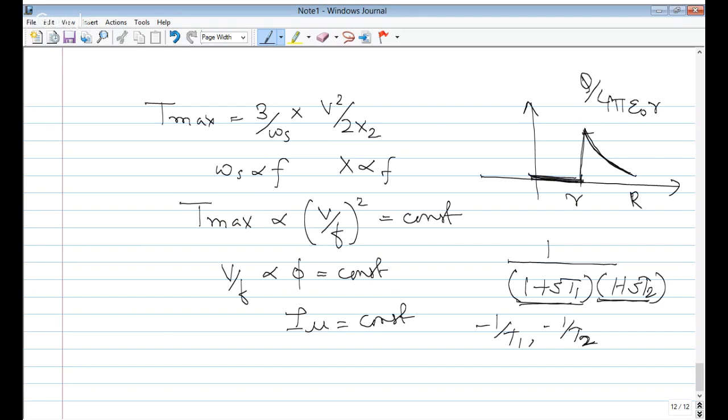One minute, let me think about it. A waveform shown as input is applied across the primary of a pulse transformer which has 1:1 turns ratio. The output on secondary side. So we know that the input voltage is basically equal to the EMF because there is no voltage drop in between.